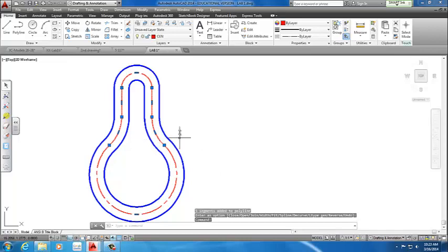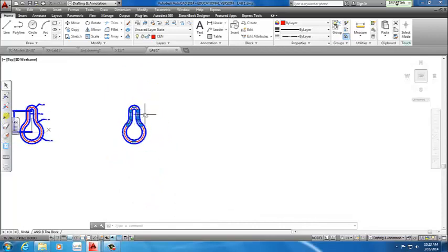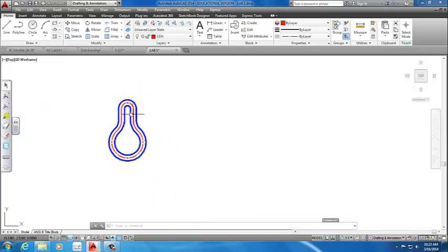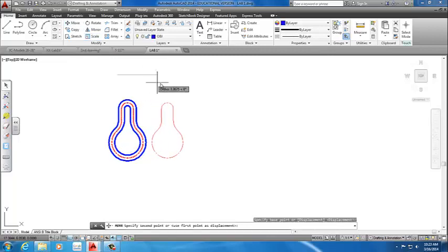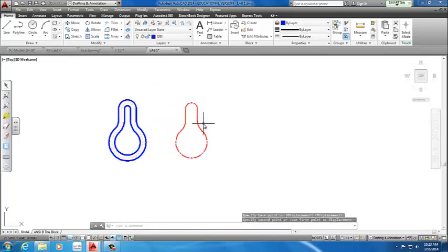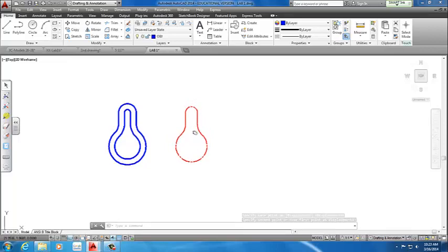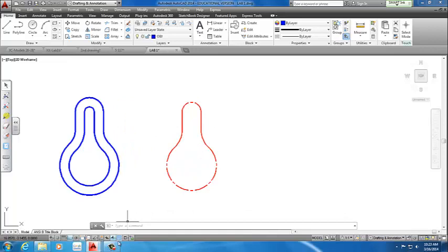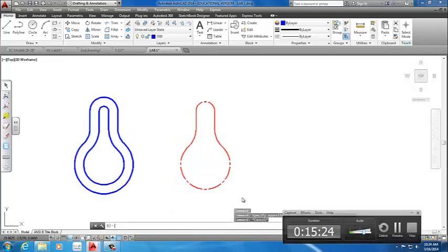At this point, my center line becomes one piece. When I click on it, it's just one piece. To prove that to you, I can just select it, which I would recommend everybody do, and just move it over. If the entire piece moves over, you're perfect. You're set correctly. That's what you want. So make sure you have that. I'll walk around and make sure everybody has that.